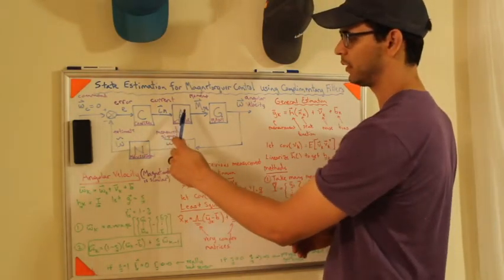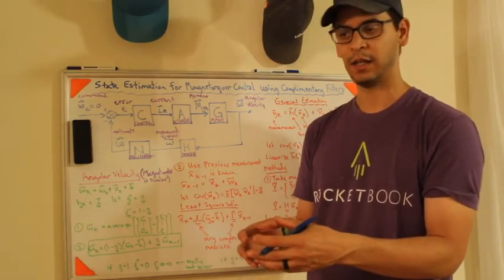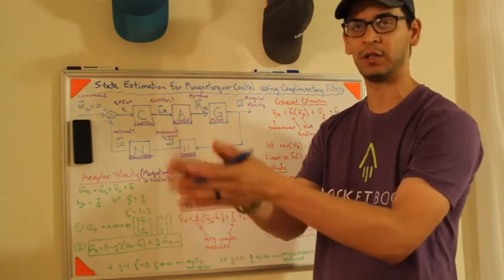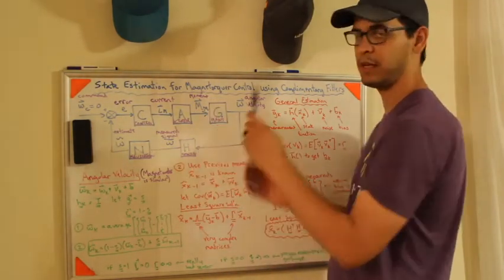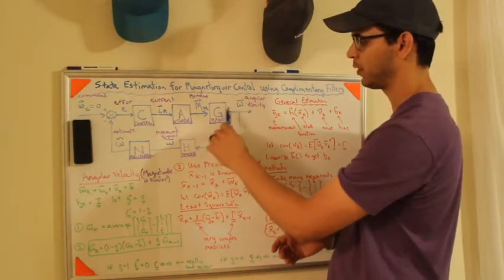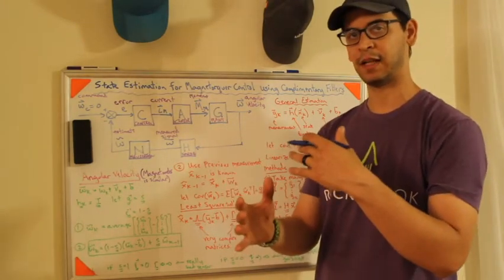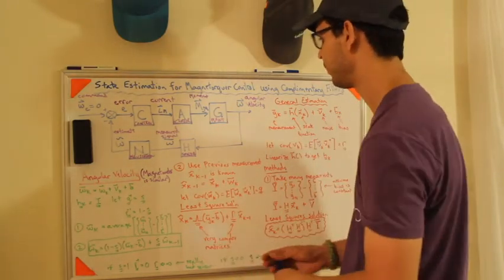That current is going to get sent to the actuator. In this case, the actuator is whatever circuitry is actually going to create the current to run through the coils. That is basically going to create the moment, or the magnetic field, that is going to get put on the plant. The plant in this case is the spacecraft, and that's going to start detumbling the spacecraft.